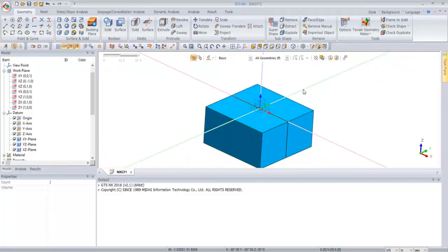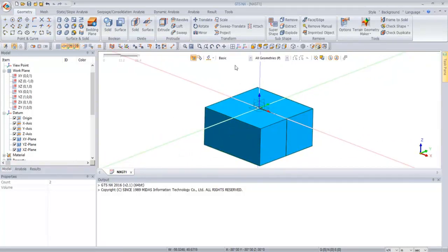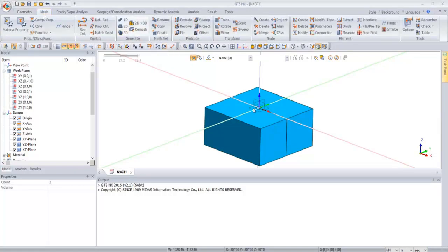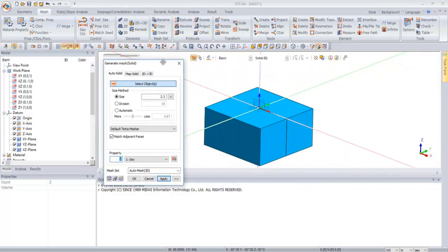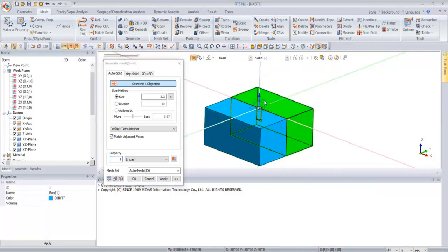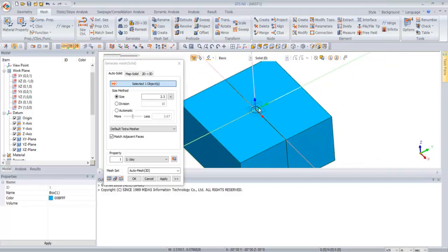As of now, everything we're going to mesh is going to be with the clay material because they're all 3D objects. Later on, we're actually going to also mesh the 2D pile faces, but as you may know, suction piles are actually hollow inside and they don't have a bottom face, only a top face. So we'll show later how this is achieved when we're trying to model those kind of geometries. For now, let's focus on the soil only, since the inside of the pile itself still only has clay, so we will be meshing this cylinder, but we'll be meshing it as clay, and we'll just call it inner soil.